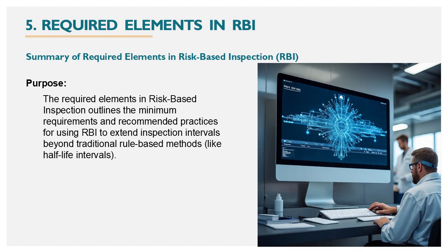Agenda number 5 is required elements in risk-based inspection or RBI. We'll go over the essential components that must be included in any RBI program such as risk assessment methodology, documentation, and team competency. Summary of required elements in risk-based inspection or RBI. Its purpose: the required elements in risk-based inspection outline the minimum requirements and recommended practices for using RBI to extend inspection intervals beyond traditional rule-based methods.